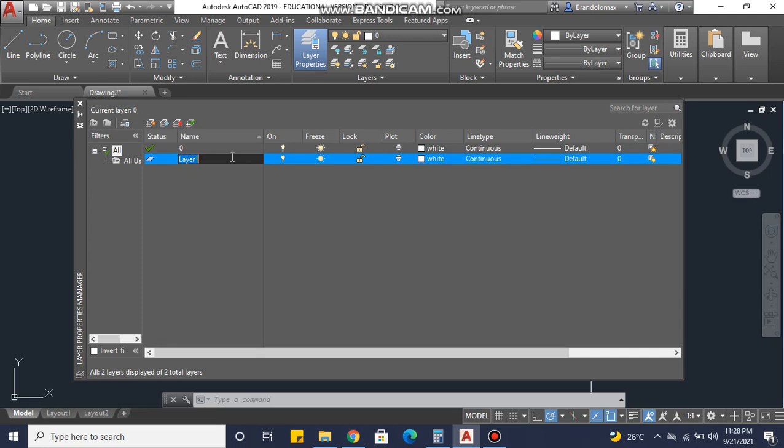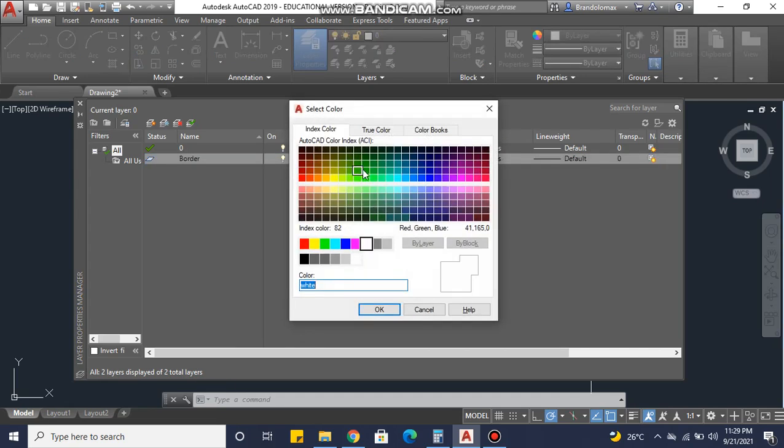Right? So if you see that there might be another layer that you would like to add to your drawing system, you can go ahead and insert that. If you think that there's one that you may not use, you can leave that out. If there's one that you would like to edit to suit you a bit, you could go ahead and do that as well. So my first layer is usually the border layer, and I usually give that a color of dark green.